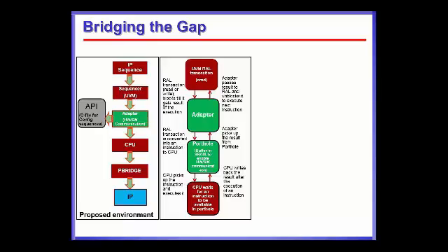to different peripherals. And if we decode that to the components at UVM level, there is always a UVM RAL transaction that would be initiated in order to access any IP through its registers. So that adapter will convert that RAL transaction into an instruction and write the details in the memory.